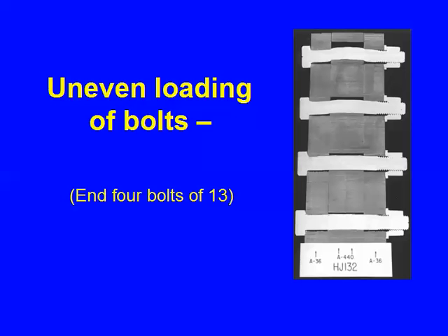For a big prize, what can you tell me about this? I'm trying to get you to think, and it would be nice if you could do the answering right now, but I realize that we're not in that position. But what is there about these 4 bolts at the end which are part of 13? Well, I've tried to encourage you in the last few minutes to think about deformations. Look at that top bolt. Look at the deformation. Look at, let's go 4 bolts down. Look at the 4th bolt down. Look at the shear deformation. They're very different, aren't they? What does that mean for us?